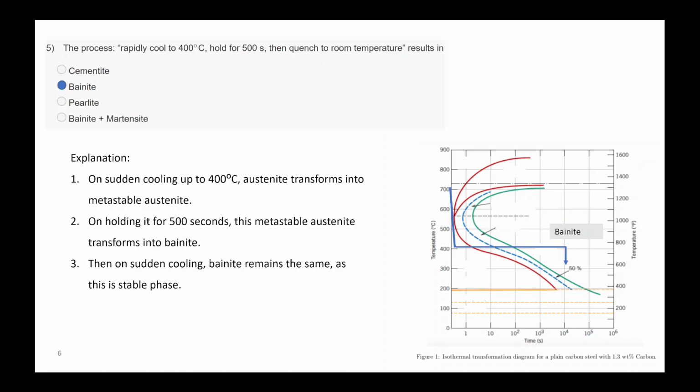But when you talk in terms of fracture mechanics, then you are assuming that porosity or some other defects are already existing. That's why the fracture toughness that you get will be lower compared to what you get using either these theories or the engineering stress strain curve.